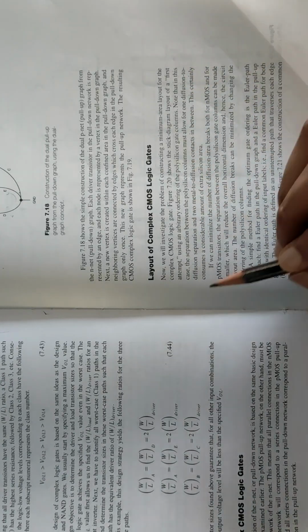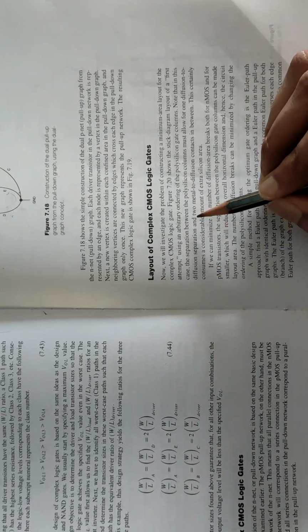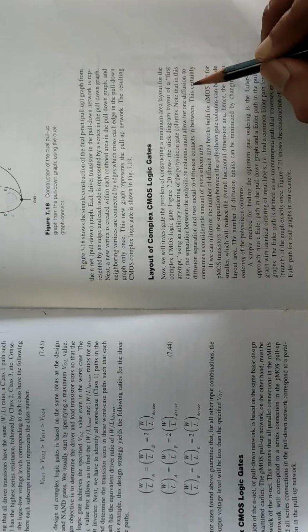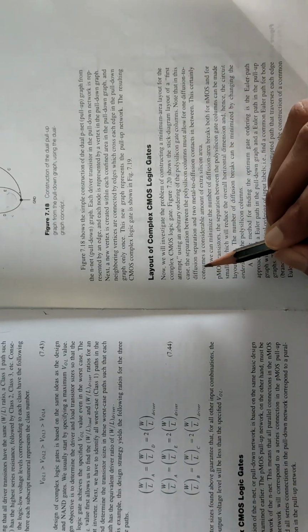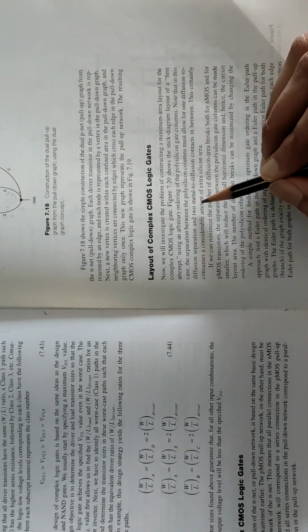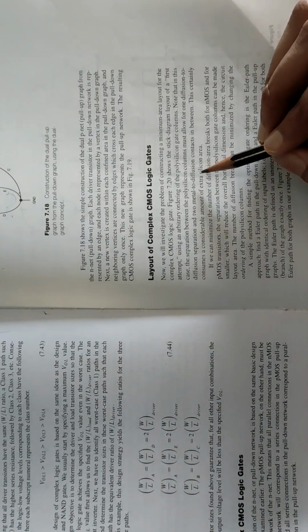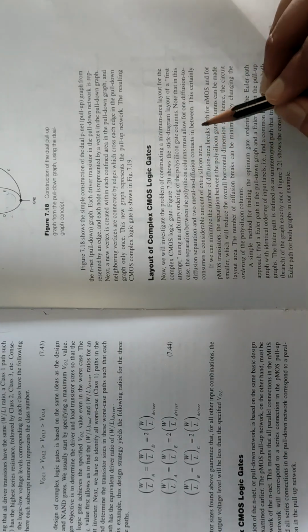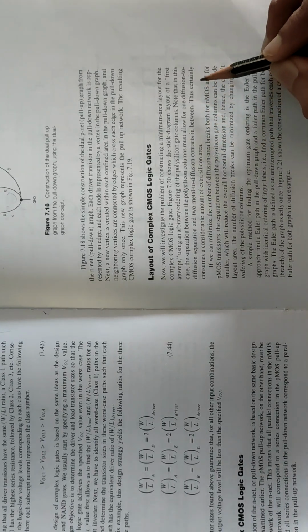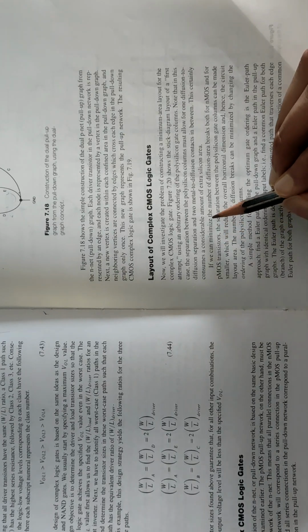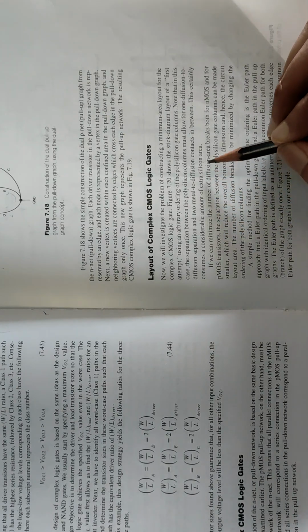Note that in this case the separation between polysilicon columns must allow for 1. diffusion separation, and 2. metal to diffusion contacts in between. This certainly costs a considerable amount of extra silicon area.